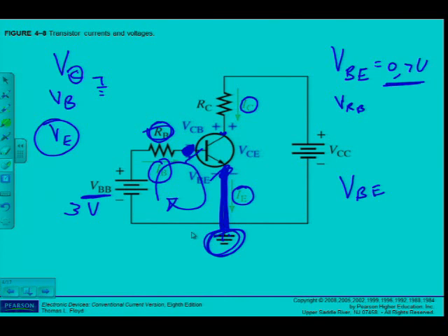Alright, the same applies for the series circuit on this side. Kirchhoff's laws and Ohm's laws still apply, so I can calculate the voltage drop over RC. What is the voltage drop over RC? By using Ohm's law, IC and RC. V is equal to I times R, so I must have the values of IC and RC. But I can also calculate the same as I've done by calculating VRB by using Kirchhoff's laws.